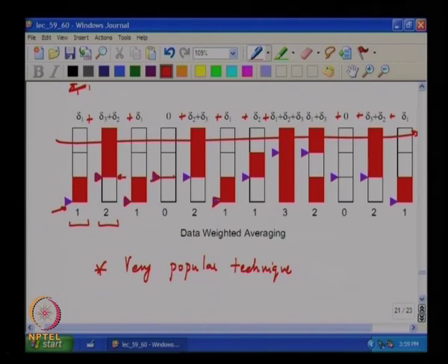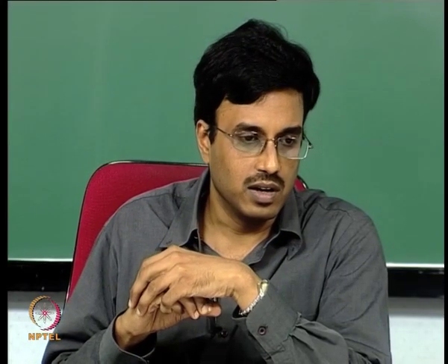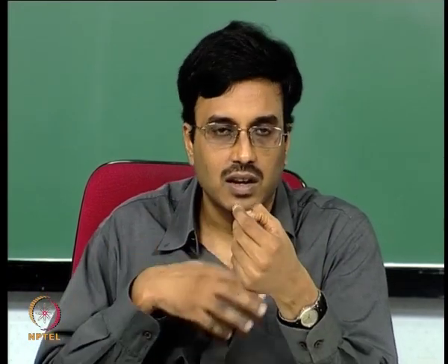Yes, no, all right. It turns out that you can show rigorously that if you want a unit element type DAC to be insensitive, or less sensitive, to mismatch, then each one of these drive waveforms must be a linear function of the input plus some shape noise type component.